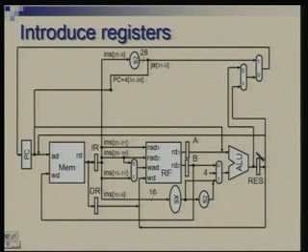What else is the ALU doing? The ALU is doing normal addition, subtraction, and or SLT operations. So, that data will get stored in this register before it goes to the register file, and also the memory address which is being calculated for load store instruction will be resting in this register before it goes to the memory. And also for a branch instruction, the next instruction address which I calculate by adding the offset will sit in this register before I make a choice here whether to take PC plus 4 or PC plus 4 plus offset. So, that is the purpose this register will serve.